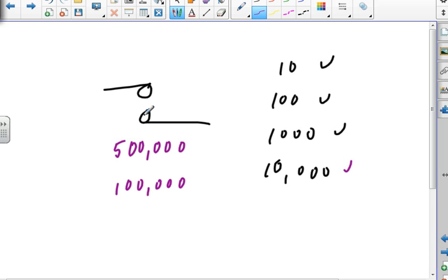And with that depositing of the copper on the switch, there's going to be some time between now and 1,000,000 cycles where it's not going to work anymore. Now, if it's an expensive switch, you can get a piece of sandpaper, sand the corrosion off, and it'll work again for another 500,000 cycles. If not, then you're just going to have to put a new one in.